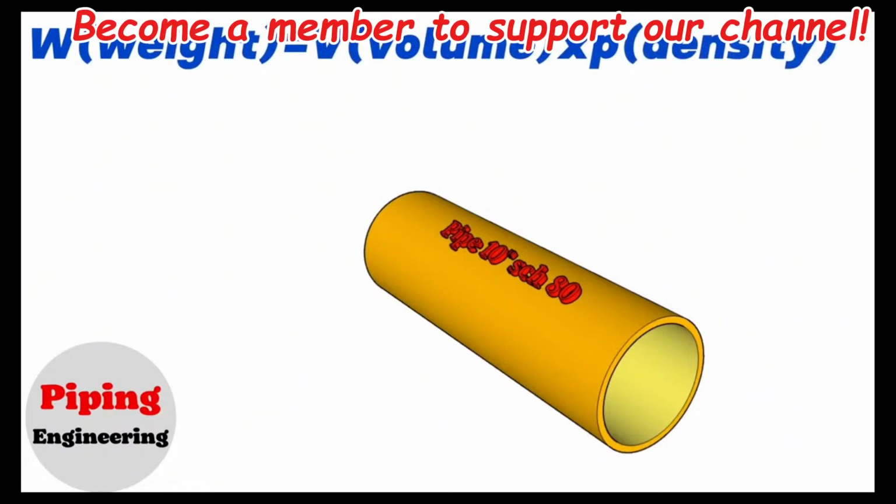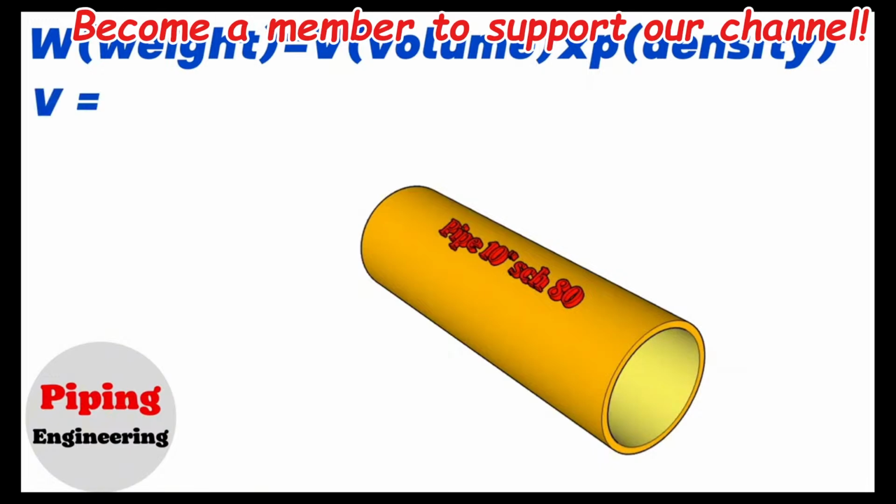In this formula, the density of the material is taken from the density chart of the materials. We have to calculate the volume ourselves. To calculate the volume we will use this formula. The volume equals pi multiplied by, in brackets, the square of the outside diameter minus the square of the inside diameter, divided by 4, multiplied by the length of the pipe. This formula applies to all pipe sizes.